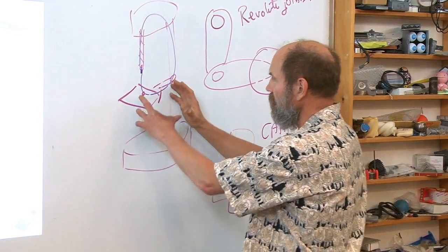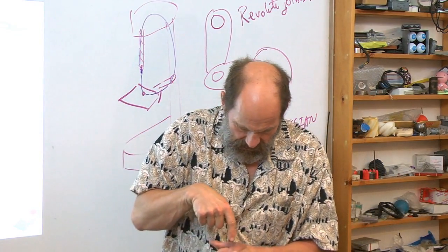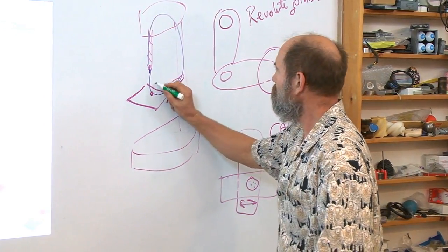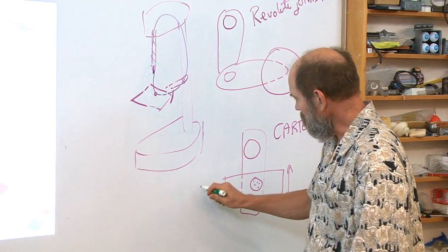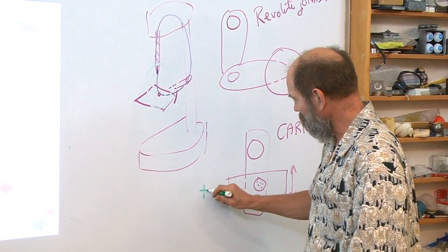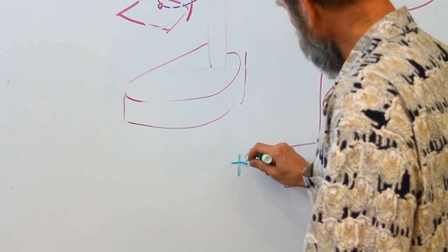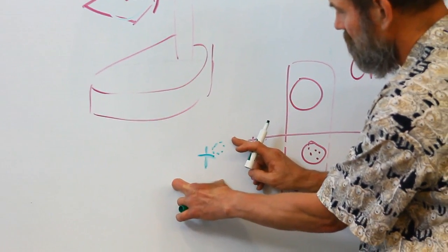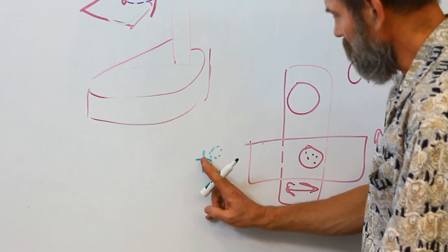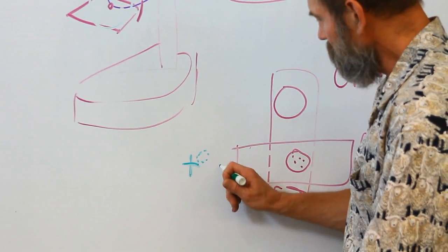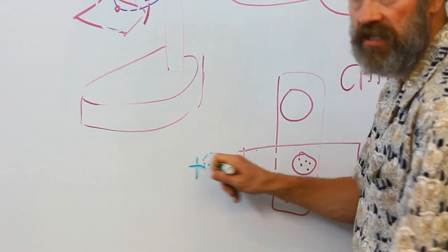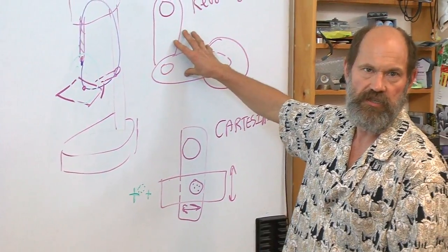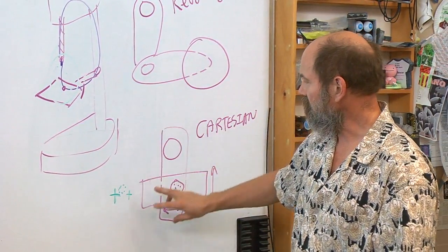And resolution is if it's here and my drill, I'll use the microscope here, blow this up, and here is where I want to drill my hole. But the drill bit is over here. Can I move the table under this, or the slightest little motion, and whoop, the table moves over here. And now you get into this hunting business. How do I write the equations and do the analysis to make sure the mechanism will do what I want it to do?